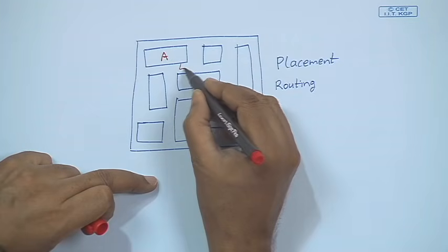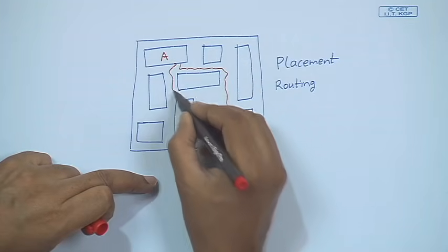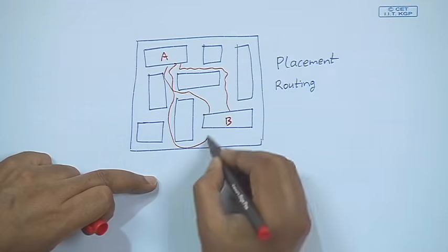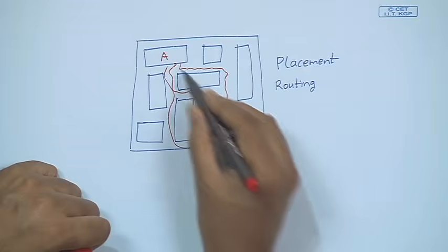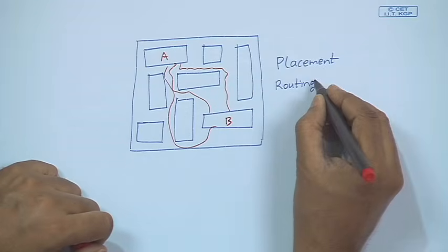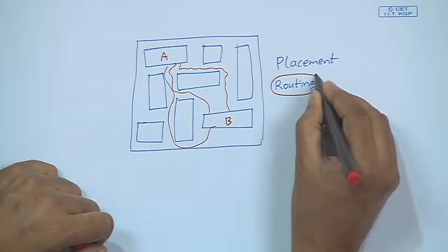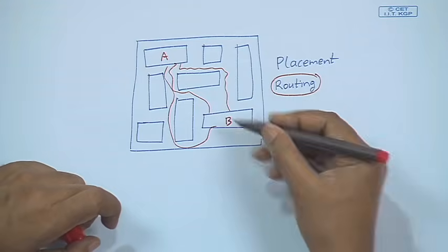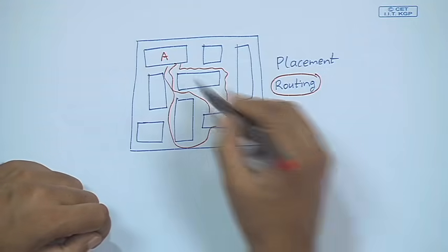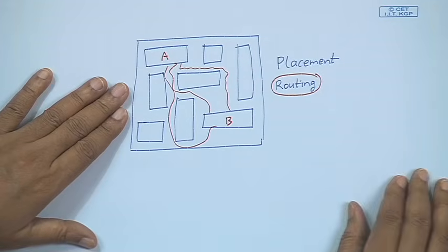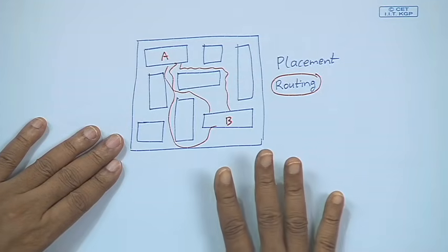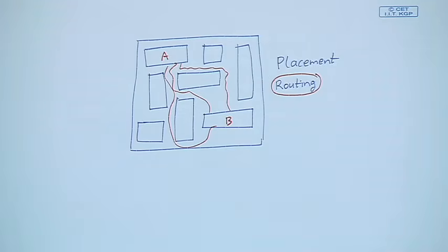So, all these connections have to be brought either from here or from some other direction. So, if you do not have sufficient space here for the connections, you may see that your routing fails. So, if your routing fails, you may have to go back, modify the placement and again retry. Okay. So, this is not a very easy task, this is quite a difficult task. All right.